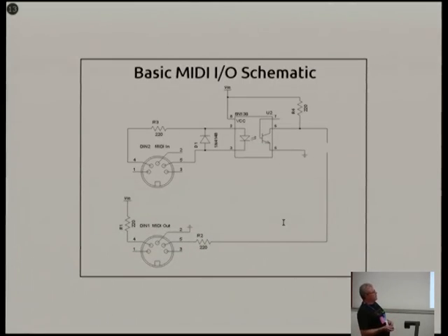I'm jumping in a little bit technical here just to give you a quick overview. It uses DIN plugs. It's always got an optocoupler on it. The idea is that no signals, hum or any kind of static can get carried through into any other equipment. That's pretty much mandated by the original standard. So everything goes through an optocoupler. And that's really it. Then it's just like a serial port coming out of there.